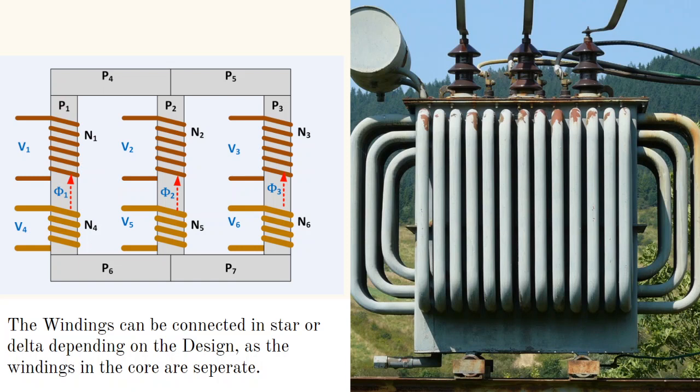Now, understanding the exterior of the transformer is different. On the right side you see it. On the interior, I have my three voltage coils of primary and secondary. The turns ratios, yes, differ. Now I can have it configured either as a star configuration or a delta configuration. For example, if I connect all these first ends together and take these three other ends away, it's called a star connection. Or if I take this end and this end connected together, this end and this end connected together, and this end and this end connected together, it will be a delta connection on my secondary.